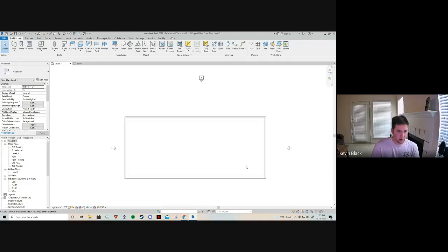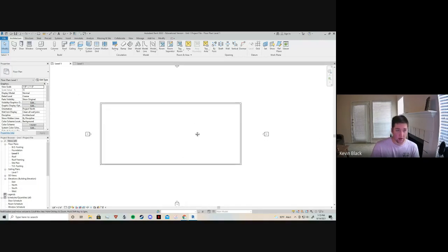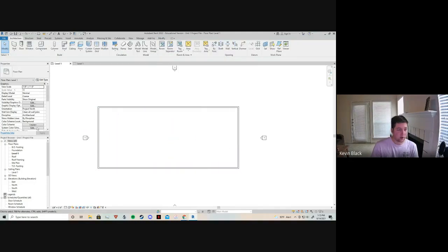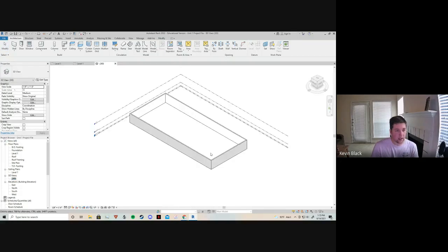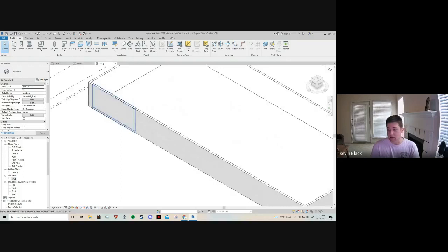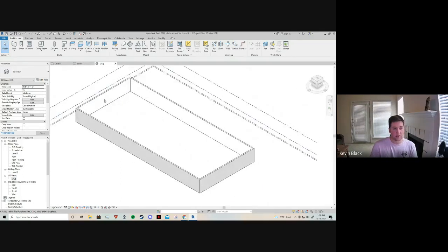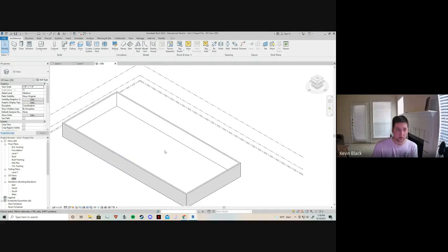So we'll use this as a go-by and call this our shell. It doesn't look all that special right now. If we go to the 3D view, it doesn't actually show us any differences between these walls because we haven't made any changes to the wall structure. But this is set up now to where when we do change those different wall types to account for the different structures, the different surfaces, the different heights, it'll automatically calculate all those things and replace these walls with the correct ones.